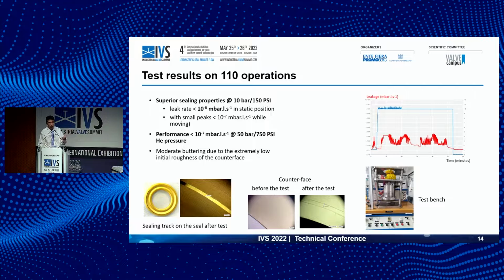For example, for sealing some valves for molten salts. It's a new application at 600 degrees. Sometimes the molten salt can also attack the graphite. But usually you have a very aggressive media. You have high temperature, but usually the pressure is low. So with the molten salt, when you reach 25 bars, it's already high, in fact.